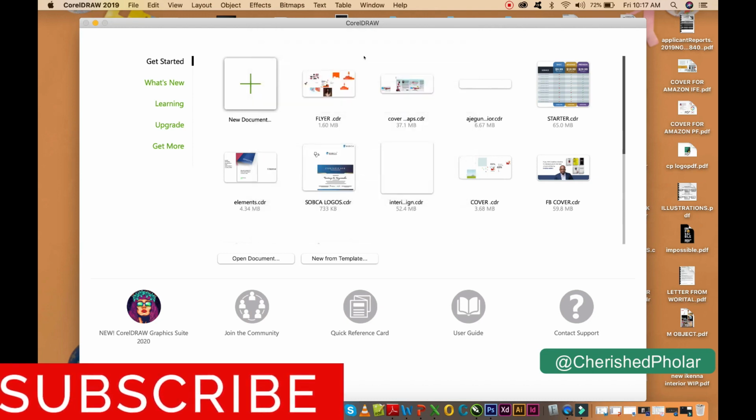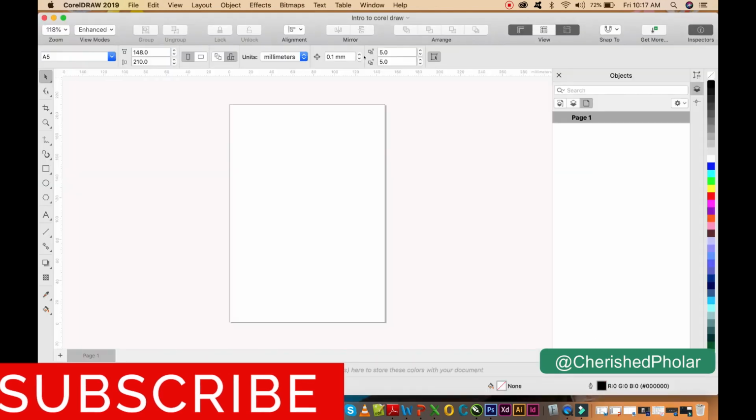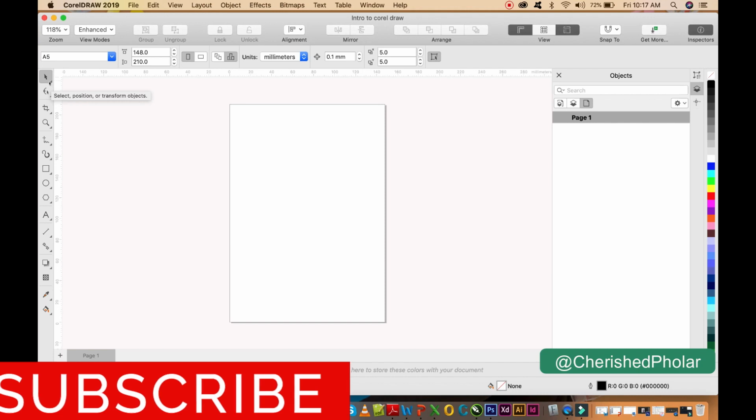Okay, let's go there. All right, so we're here. This is what will happen once you click on that, and you're going to see everything around the CorelDRAW interface. So I'm going to be walking you through some of these tools. We call these the pick tool, select tool, or position tool, basically you use this all the time. Even when you move to other tools, you still have to come back to this to get things done, of course.